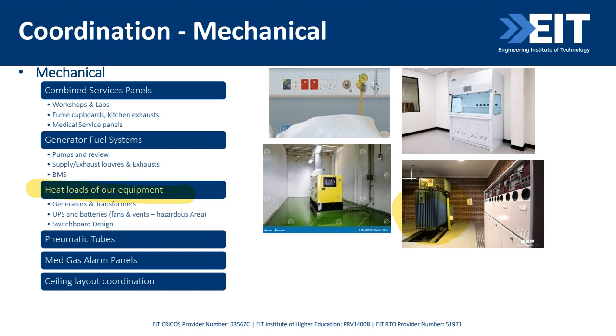When we say ceiling layout, we mean when you look up at a ceiling, you might see lights, you might see mechanical extraction fans, you might see AV speakers, you might see cameras, you might see sensors. All of those items need to be coordinated on the tiled or the plasterboard ceiling to make sure that they don't clash. So this one is quite common.